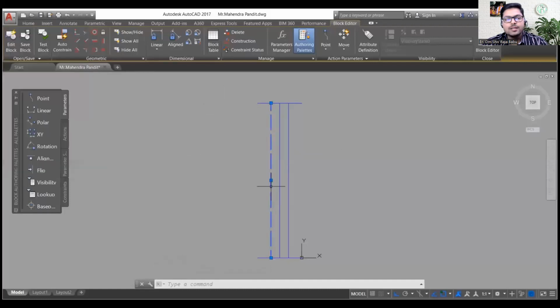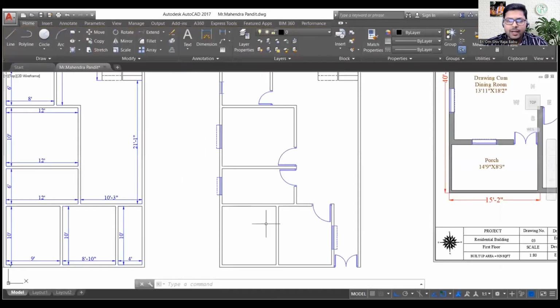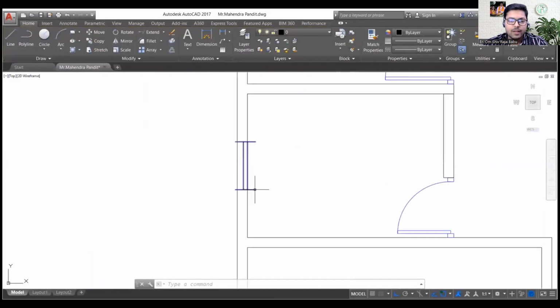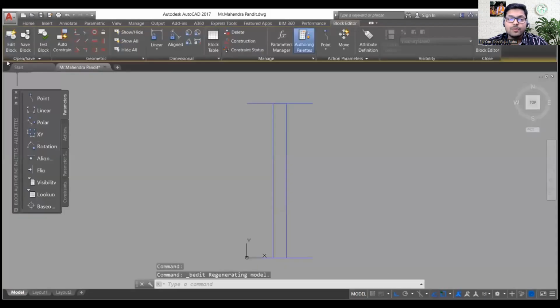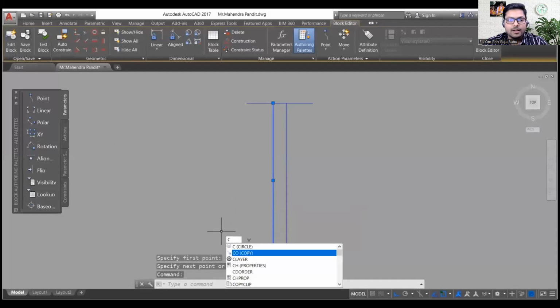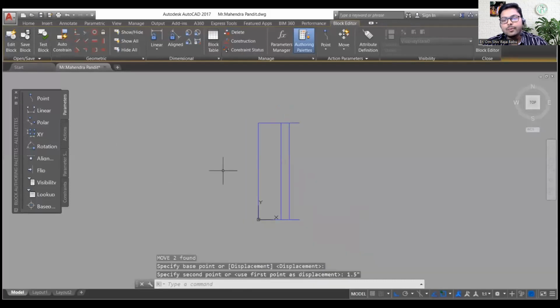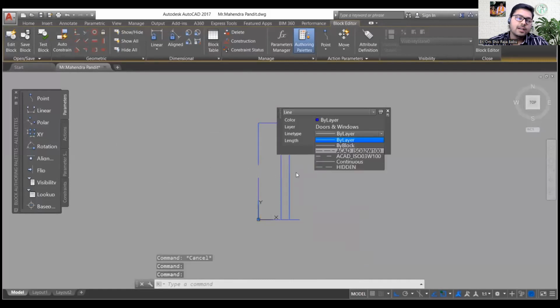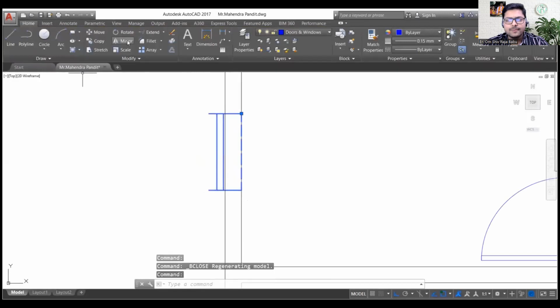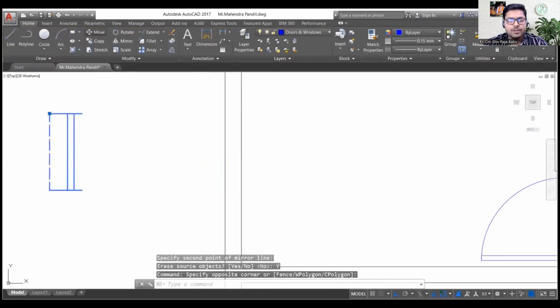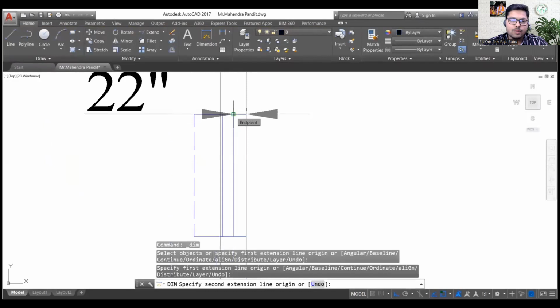You can also change the scale of the line type to make your drawing look more appealing. In this one I'm also adding the chajja over there so that it can better suggest how far I can extend. And in the left side, I already told you in the beginning that my plot was 24 feet by 120 feet, but the front that I am taking over here is 23 feet 6 inches. So for that 6 inches I can just leave the chajja. I can use that 6 inches wall thing over here.